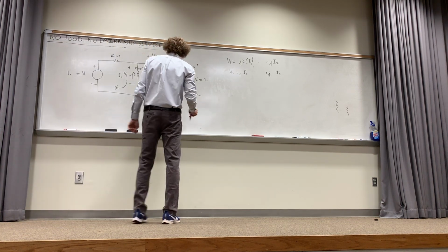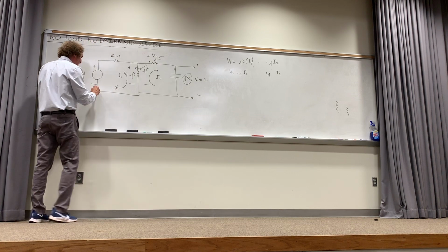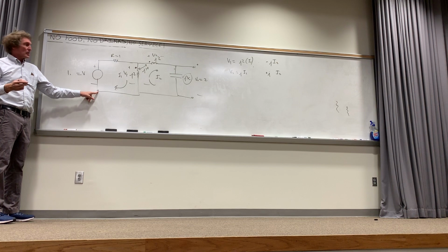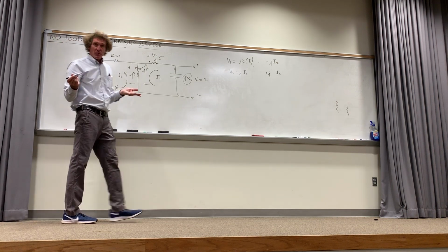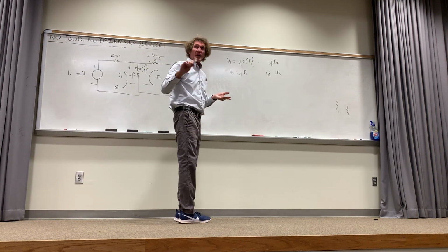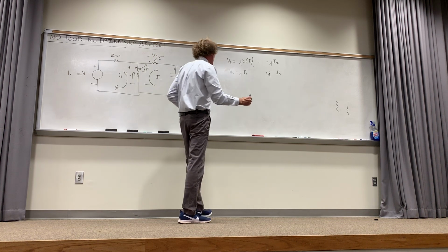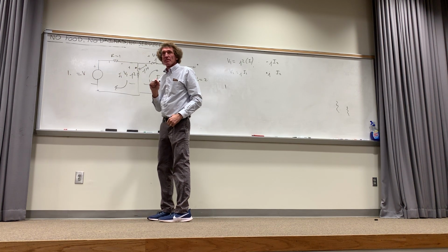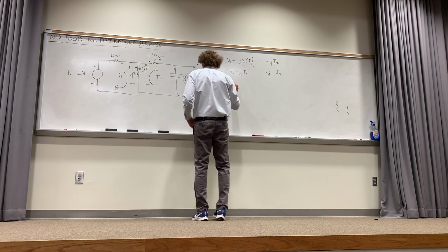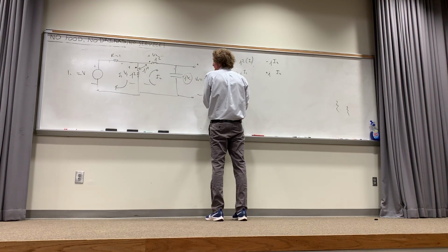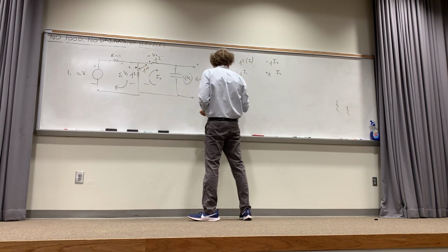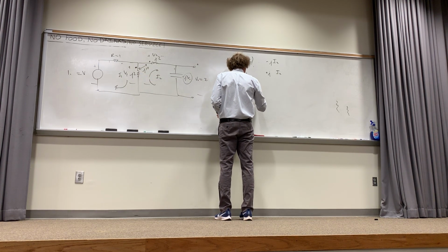Now, what I'll do is start the loop, go around the loop right here. I'm going to go clockwise around the loop. When I do this, I get a voltage increase of 1 volt. Do you agree with me, class? Because I made V 1 volt, didn't I? So I've got 1, right? And then this is going to be a voltage drop here, right? You all see what I'm doing, don't you, class? So it's going to be minus just 1 times I1, or minus I1. And then it's minus V1 equals 0.